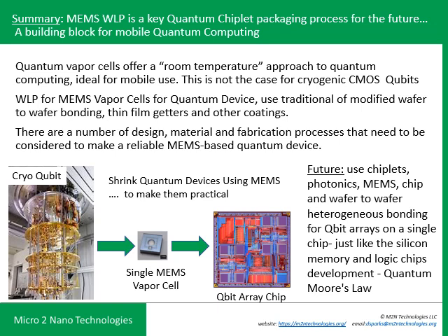So there's a number of wafer level packaging challenges that have to be overcome or addressed to have a hermetic, reliable seal, to eliminate trapped gases, to eliminate a number of things, both at the chip and package level, that can lead to quantum decoherence. These include the trapped gases, magnetic fields, electromagnetic interference, things like that that can be addressed at the package and chip level. And these have been addressed at the package and chip level with other MEMS devices. Now, the challenges are harder for preventing quantum decoherence. There's no doubt about that. But I think there's a path forward with this.